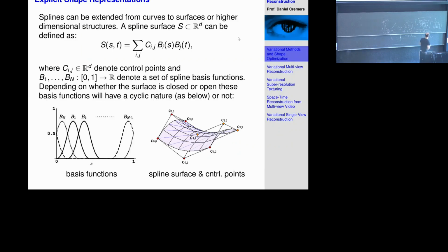And so this is the parameter interval, these are the parameters little s and little t, and for any (s,t) I have a mapping that maps to this surface in R3. And this is what this mapping looks like. And so here again you have that surface that you see here in purple, and then the little red control points, and you can imagine if I move them a little bit, then the area in the vicinity will move along accordingly.